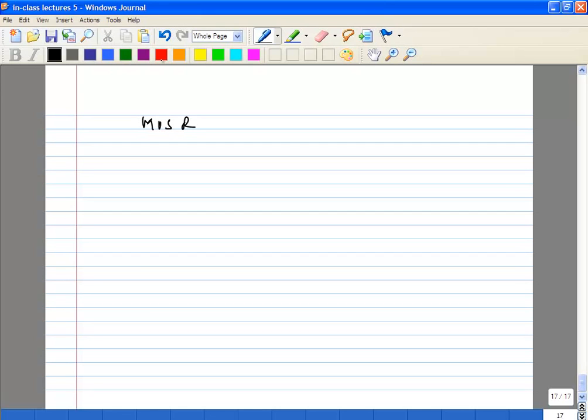Obviously, we looked at this during the VCO. MOS resistor, if you want really mega ohms kind of resistance, you can use this. You can use a MOS resistor with a very small W over L.